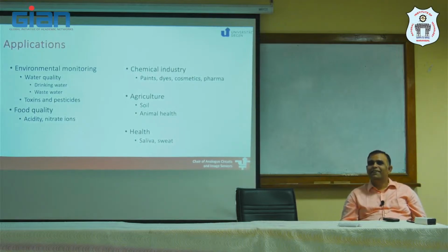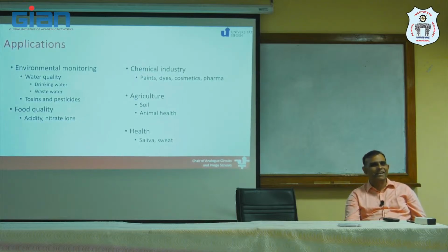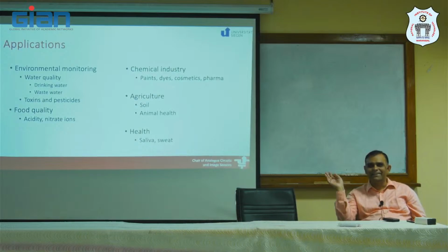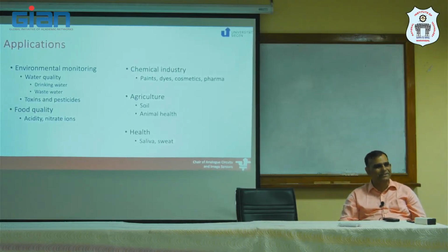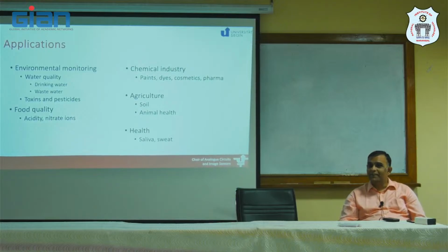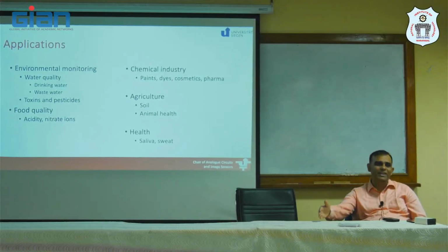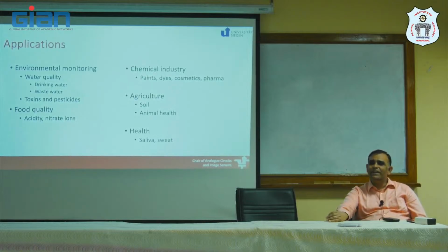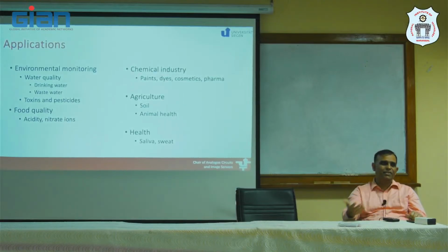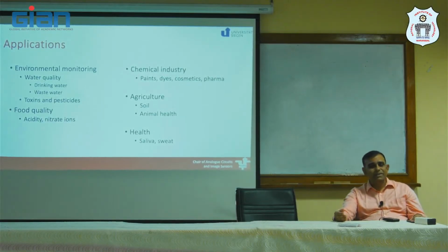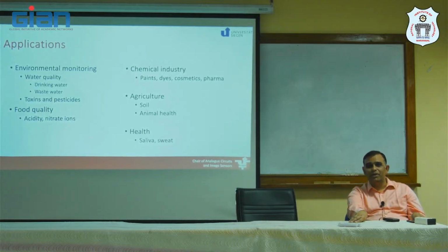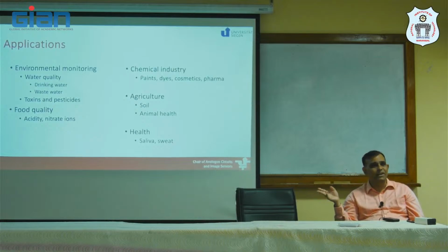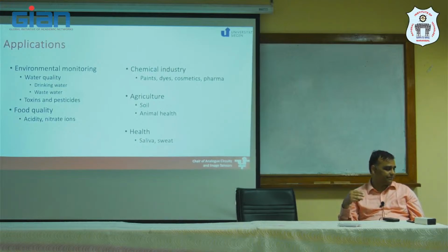Now in one slide, I have gone through a large range of chemical sensors. Remember, in the beginning I said chemical engineering is big. I won't be able to cover it. So I said, okay, let's ignore everything and just talk about a transistor-based sensor. Once I could measure pH of liquid, I can use that in a large range of applications. In all of these applications, of course, the rest of the instrumentation will be slightly different, because it depends whether you're looking at acidic or neutral and what you are doing with it, but the fundamental circuitry building block will be very similar to the 3 circuitry blocks I have shown: either a voltage readout, a current readout, or a charge based readout from these devices.